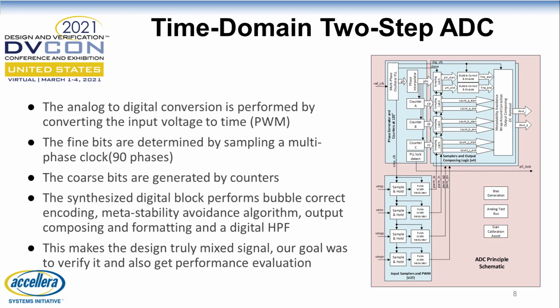For a high-resolution ADC at an advanced node, there is a problem with the traditional approach as supply voltage goes down and limits the dynamic range of voltage domain signals. On the other hand, you have the advantage of fast technology because the whole technology is biased towards digital design. This has led recently to the proliferation of time domain circuits that profit from the speed of advanced nodes.